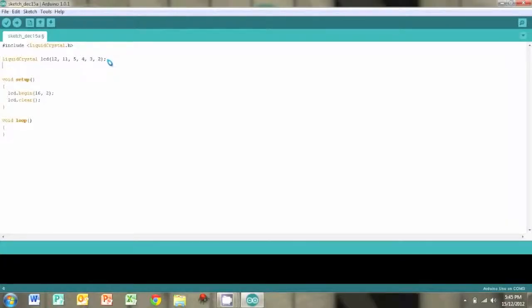So the first thing we're going to need to do is create an array of bytes. And since an LCD character has 5 pixels by 7 pixels, the bytes are going to be 5 pixels long, and there are going to be 7 of them. I've just created enough space for an extra one, just in case. So 5 pixels. And I'm setting them all to 0 right now, but if you turn them to 1, then that pixel would turn on the LCD. So there should be just one more. And we've got the commas as well between each byte.